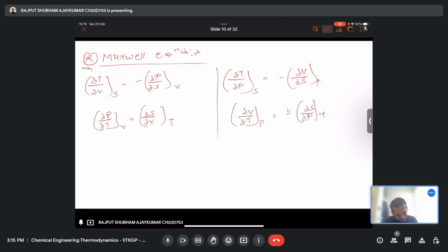Like I showed in the last week, week two and week three, thermodynamic property relationships and Maxwell relationships. Just like knowing what is Gibbs free energy, Helmholtz energy, enthalpy, entropy, and different terms, and just doing partial differentiations related to that. And you should know what is the work done. The work done is the pressure applied over the volume difference. So W is equal to the integration of P dV, from V1 to V2. Okay, this is what we have already covered, but I'm just mentioning it for a recap.